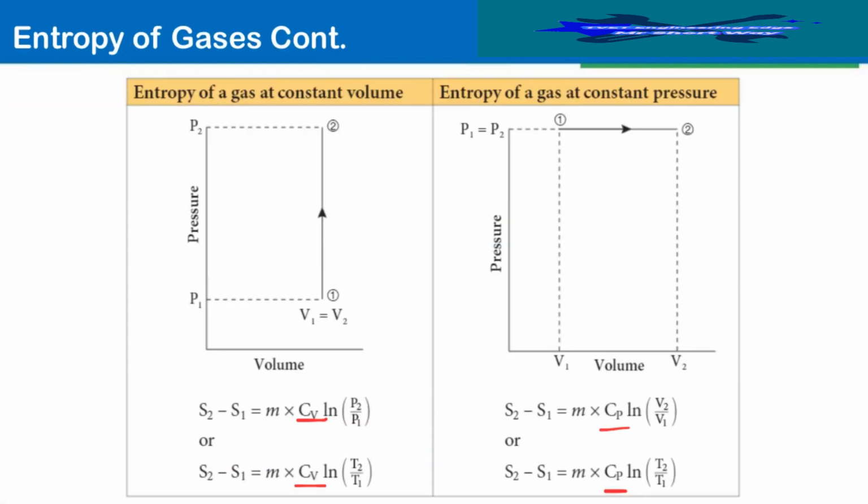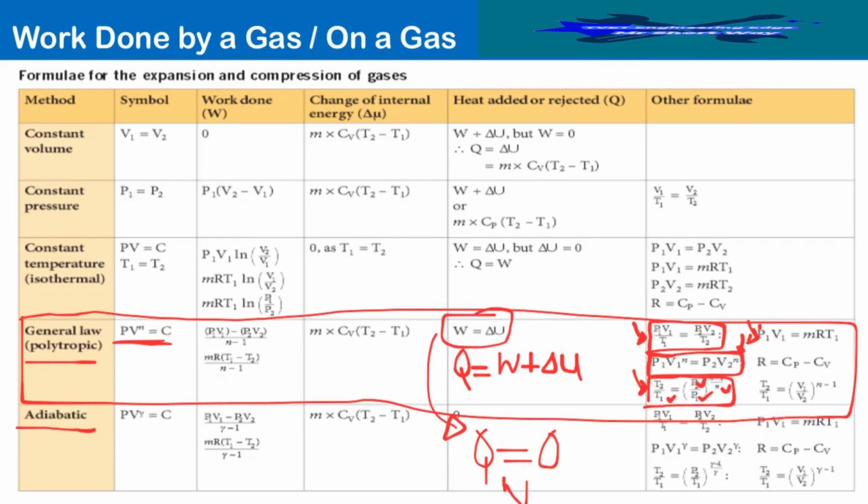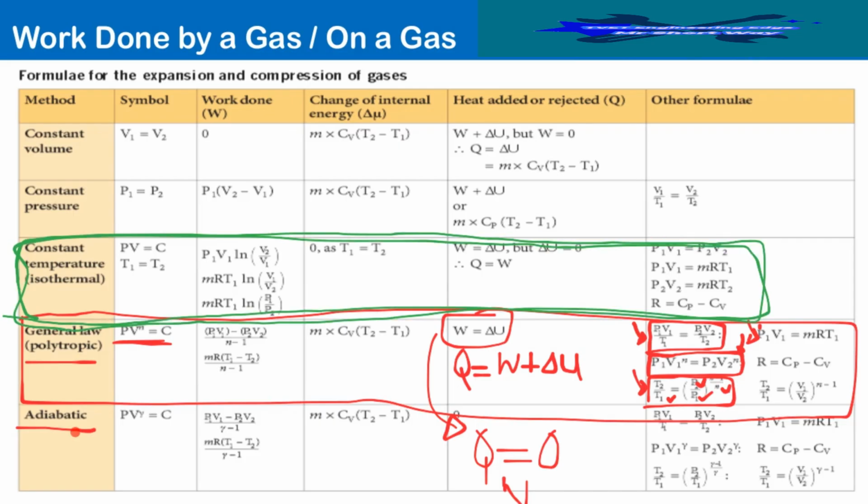All right, so we go back to our table over here. This time around, they say it's compressed isothermally, so we're going to look at row 3. What I've just circled in green is what we're going to use as governing equations. Since it's an isothermal compression, these are the equations we're going to use. All on the same page.